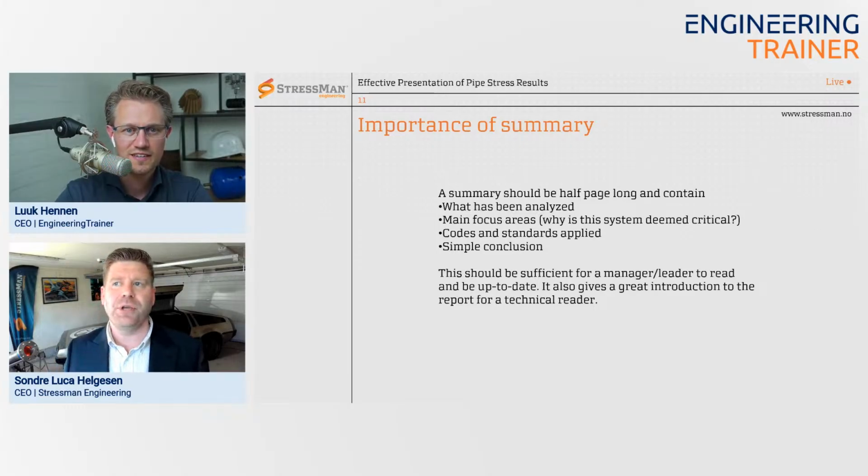In some cases, as you mentioned, we might not have an allowable load. We are just requested to report them. It doesn't happen that often, but it happened two weeks ago, and we just reported the loads. We feel they're fairly low, and then what is fairly low? Some vendors say 0 Newton on my nozzle, and I was like, yeah, dream on.